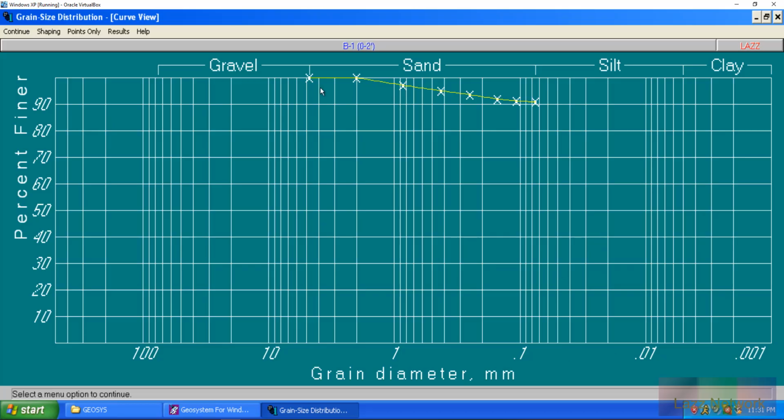Anyways, like I was talking about before, anything greater than your number 4 sieve, because these are all of our point sieves, like I discussed. This is our number 4, and here's our number 200 sieve. Technically, anything past gravel is considered cobbles or boulders. That's the general synopsis engineers will say, but usually engineers don't really care about sizes that big.